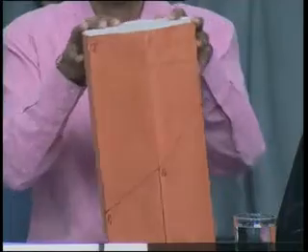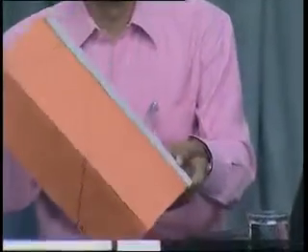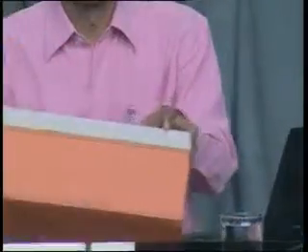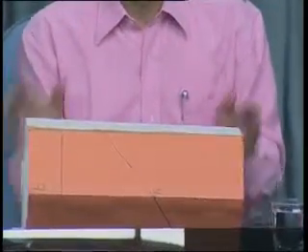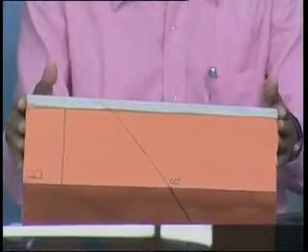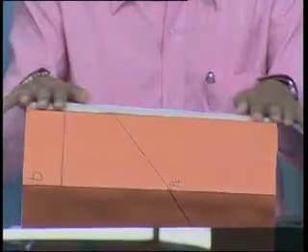After drawing this top view, we will tilt this like this, right? So this is the first view, this is the second view. Tilt this at a certain angle and make it such that it becomes parallel to the XY line. After lying it over here, put it over here, draw the third view or draw its front view like this, then take projections and find out its true shape, its top view. It would be like this, right?